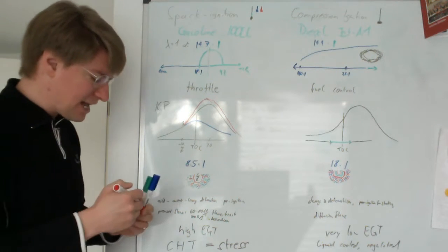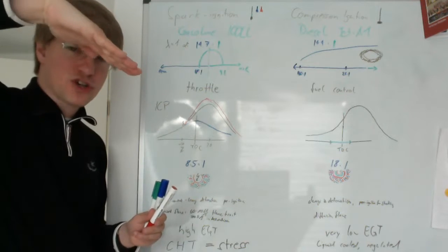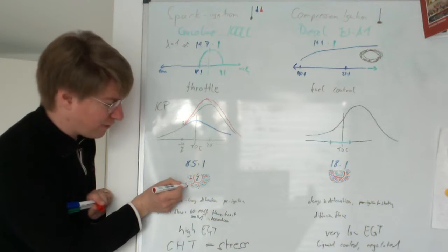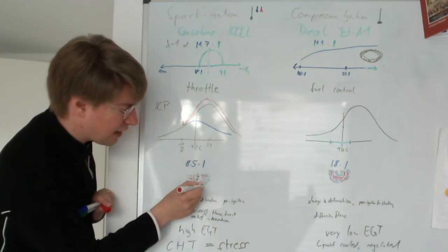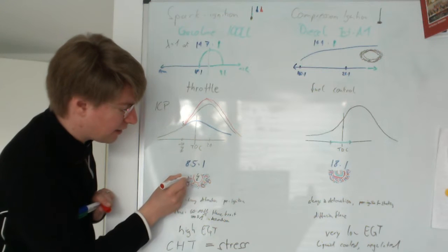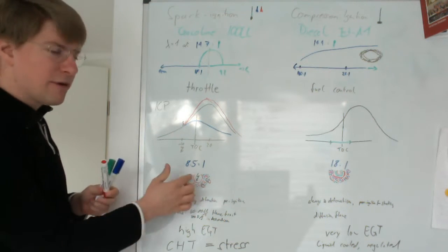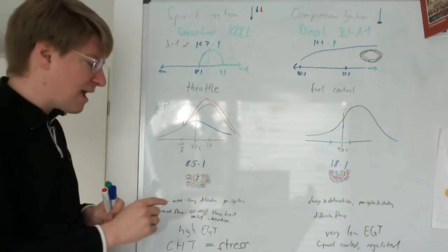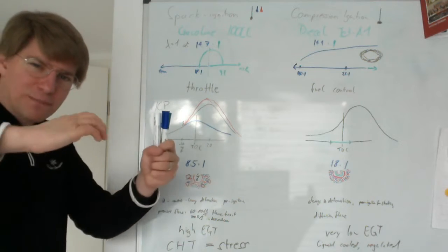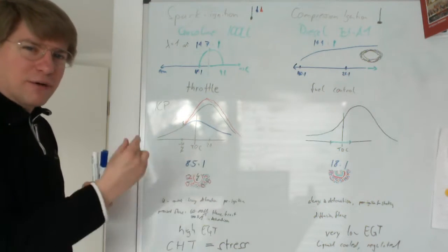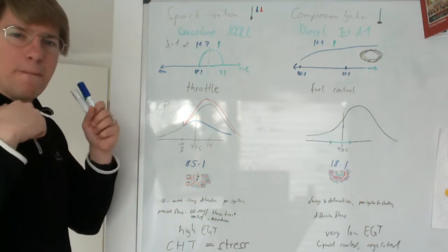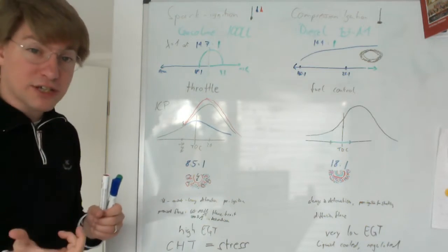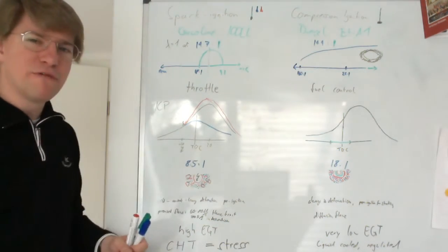All right, so if we mess with this and get the flame front to move a lot faster, what can happen is that the rising pressure in the combustion chamber triggers combustion beyond the flame front, somewhere here in the pre-mixed mixture in the cylinder. Remember, the cylinder is filled with a combustible mixture at the optimum air-fuel ratio, and if the pressure rises enough, that combustible mixture will ignite and combust, even though that particular part of the mixture was not touched by the spark and was not touched by the moving flame front yet.